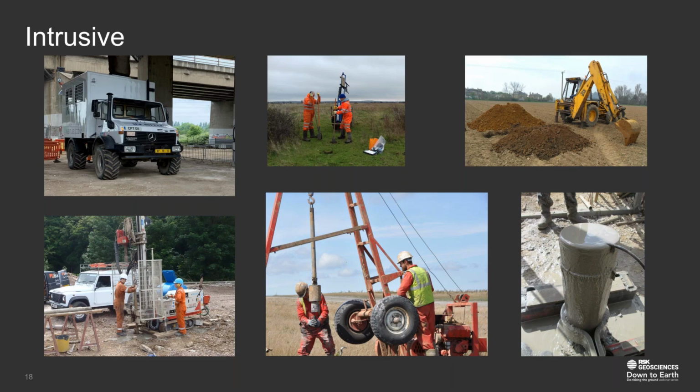Then we've got boreholes. There's different types of rig for different types of boreholes. I've shown 3 different types on this slide. So in the top middle is a dynamic sampling rig, bottom left is a rotary rig, and in the center bottom is a cable percussion rig. These drill smaller diameter holes to extract soil and rock samples. The common methods that I've already mentioned include dynamic sample, cable auger boring, and rotary drilling, but you also get percussion drilling and sonic drilling.